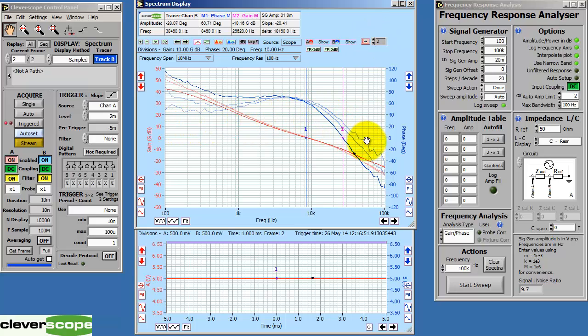So you can see that we can capture a family of curves and then probe and check the values for each curve. As you'll see, the gain and phase margin are being updated as we change through the curves. Finally, we can use annotations to label the curves. So we click the annotation tool and go over here, for example, and write 0.5 amps, and down here 2 amps, and here 1 amp.